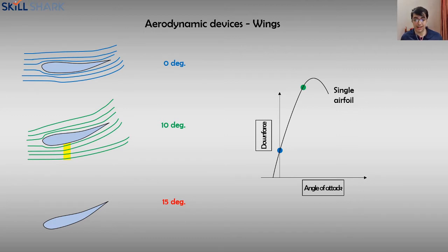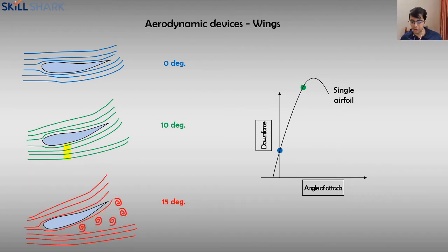When you reach an aggressive angle like 15 degrees, what happens is air completely breaks off, and that causes two issues. Of course, you have not as much of a pressure differential because you don't have much air going through this area. It's more of static air present here, right at that separation point. And then you have extremely turbulent air that's coming up over here. And generally, turbulent air has a lot of velocity. But what happens is you also have turbulent air going over the edge of this airfoil, because at this point, air tends to curve over the edge.